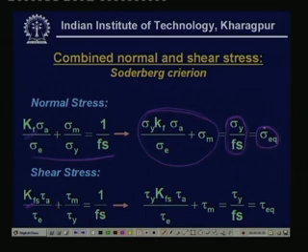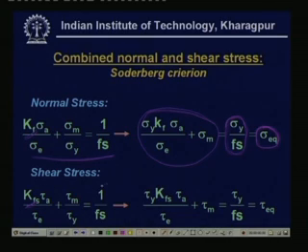That means if we can find the value of sigma equivalent, it will contain the terms of the design parameters, and if we equate it with the material property, then we get the desired design situation. Similar is the case for the shear stress equation, where the shear yield point is multiplied on both sides of the equation to give an expression of the equivalent shear stress of this nature.